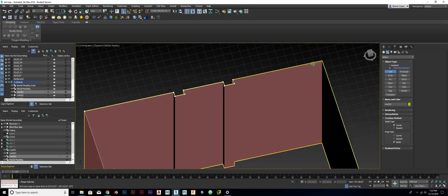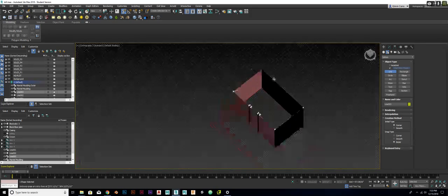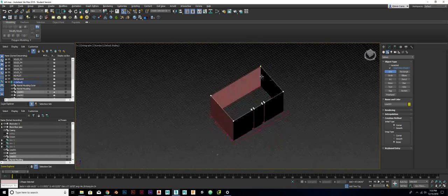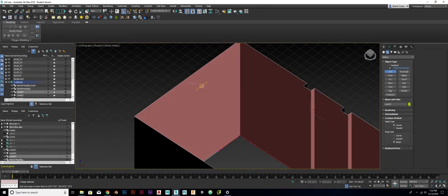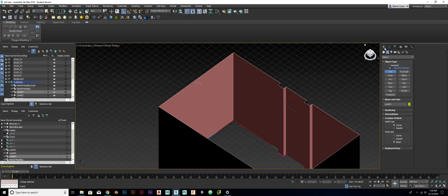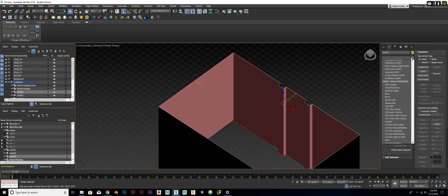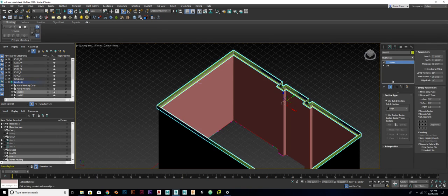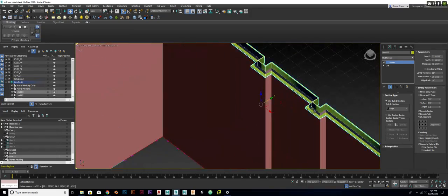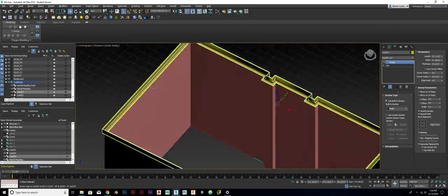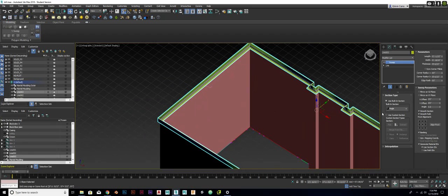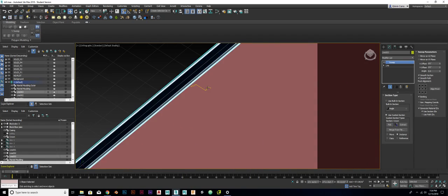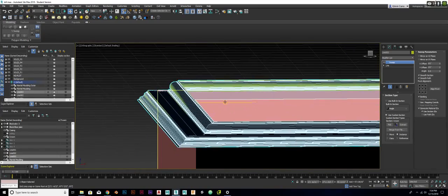Okay. Perfect. Yeah, close that. Okay, so now we got our path there. We got our profile. Things are looking pretty good. Hopefully, we'll see in a second if this is really gonna give us the desired situation here. So let's go to sweep. Alright, what is it trying to sweep here? It's got the default sweep in here. I have no idea what the default really is. Looks like some random thing. But anyway, we're gonna use a custom path. We're gonna pick our path, and that's our path there. And there's our crown, just not where we want it.